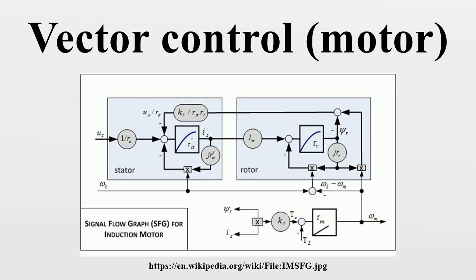A decoupling term is sometimes added to the controller output to improve control performance, to mitigate cross-coupling or big and rapid changes in speed, current and flux linkage. PI controllers also sometimes need low-pass filtering at the input or output to prevent the current ripple due to transistor switching from being amplified excessively and destabilizing the control. However, such filtering also limits the dynamic control system performance. High switching frequency is typically required to minimize filtering requirements for high-performance drives such as servo drives.